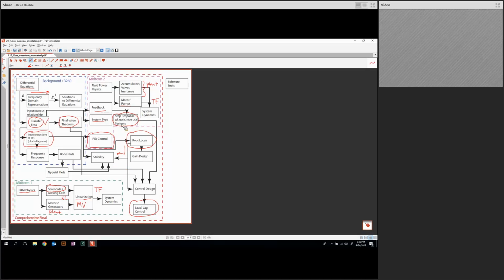And so that was a majority or major focus of the last few weeks of this class, is these root locus methods. So we could use this for stability analysis. We could use this for control design. For control design, this means that we're taking these type of forms for the lead and lag controller, say for instance just a single real zero, a single real pole, and then we can understand via the root locus methods how to design these controllers.